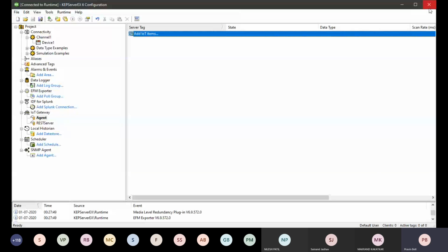So what I'm trying to tell you is, from Automation Studio, data is captured into the OPC server of a software like Kepware, and from Kepware, using the IoT gateway, send it to the cloud, and then use the dashboard of that cloud to show the data representation. That is how the entire channel should work. This is Kepware. So that is what I wanted to show you.